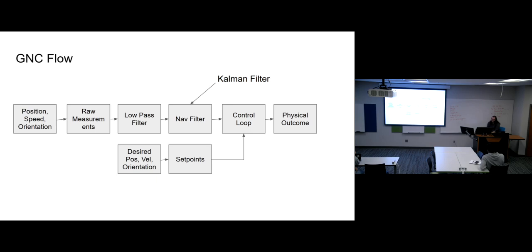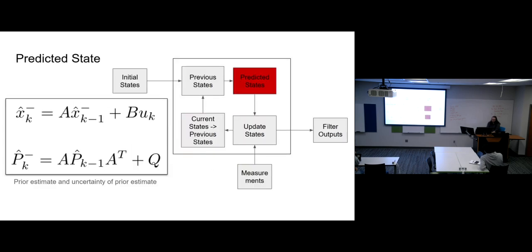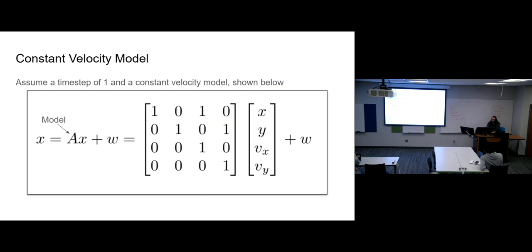If you do something like this, your model comes into play. If you think about this, this is 2 sensors in 2 dimensions, so x, y, and dx, dy. This is not accounting for acceleration. That would add 2 more, so now you're dealing with 6. Then you go, okay, roll pitch yaw, magnetometer information in there, and now you're at a 20 by 20 matrix. Now you get the vision stuff too, and you have visual odometry and all this feature extraction.